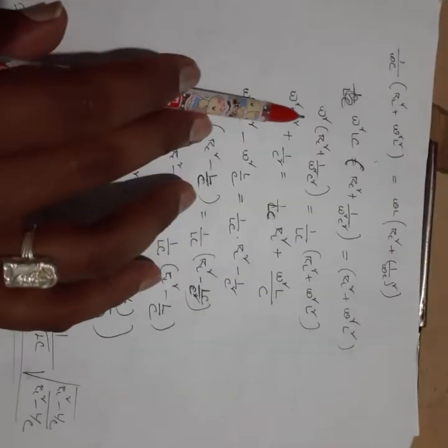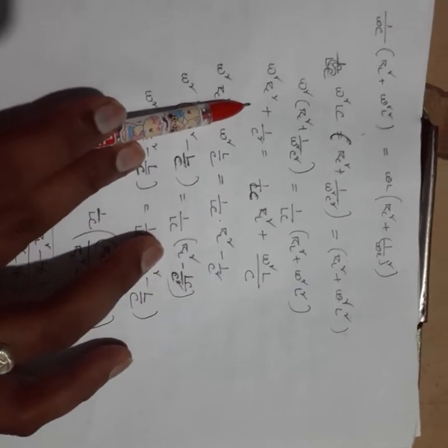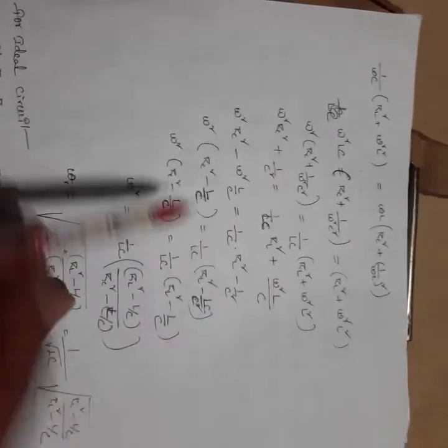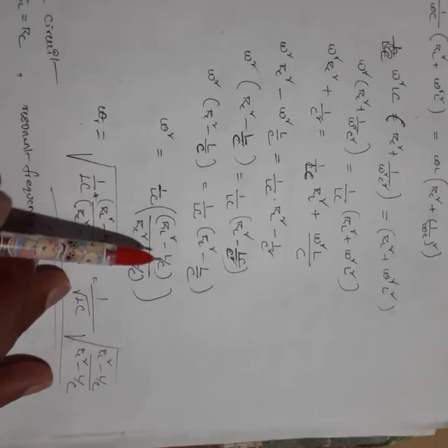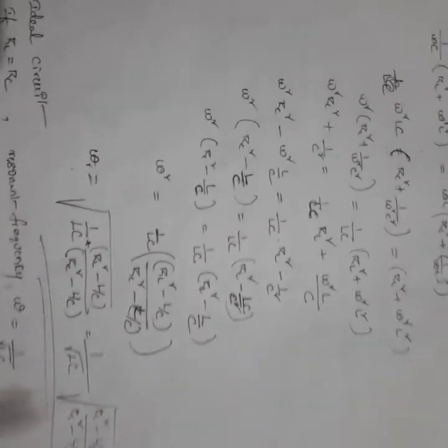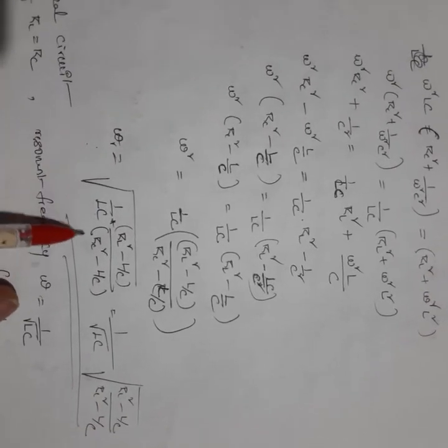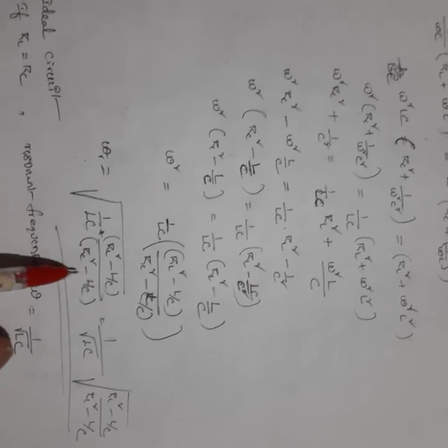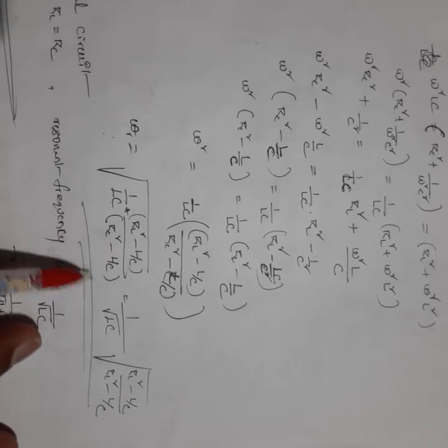By analyzing these equations and simplifying the terms, bring the omega terms to one side and the remaining terms to the other side, take the common omega and send the remaining constant to the LHS. So finally we get omega r equals 1 by square root of LC into square root of (R_L square minus L by C) by (R_C square minus L by C).